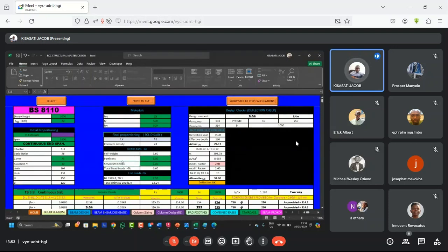Now, for the surfaces and finishes, surfaces for our buildings, we have tables, we have beds, and so on. So all those things that are giving you service, those are some of the loads that you are supposed to consider as permanent, the dead loads. So for the surfaces, we always take 1 kilonewton per meter squared. Then for the finishes, we always recall tiles, we have the ceilings, and so on, all those things, I think we will know them. So for the surfaces and finishes, we always consider 1. So the sum is 2 kilonewtons per meter squared.